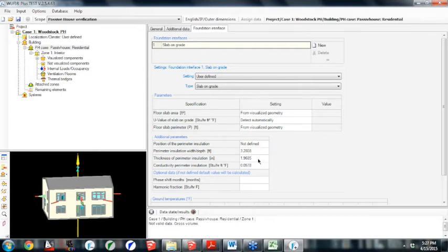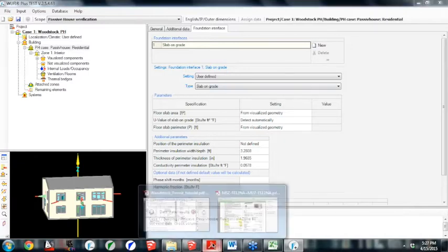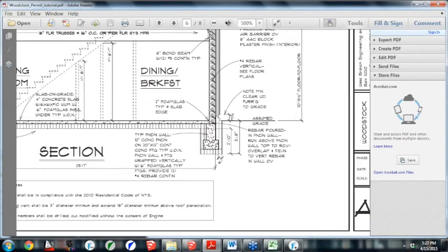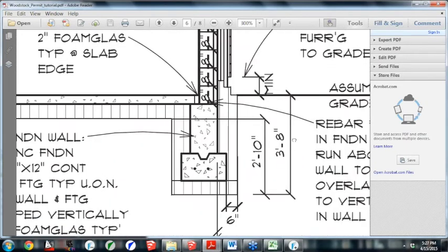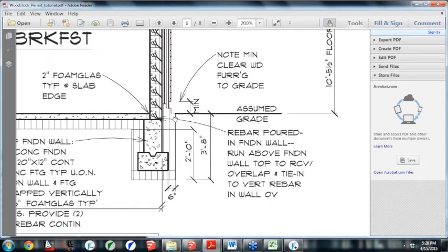So if I go back to my drawing here, here's the perimeter. It does have vertical perimeter insulation over here, as you can tell. The depth that we're looking at is beneath the actual sub-slab insulation, so it'll be this 2'10" here. It thinks right now that the slab extends with this insulation all the way out to here. It's the way the areas are input. So we're going to do everything additional to that below that. Looks like it's about 6, well, that's 6 inches, so maybe it's 8 inches thick. So we're going to select vertical insulation.